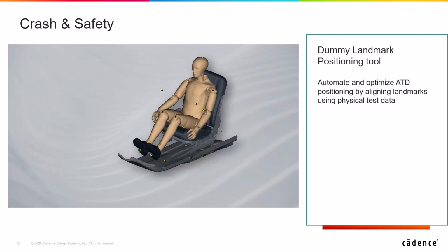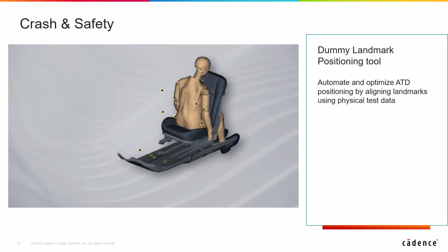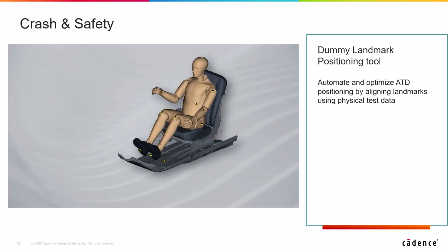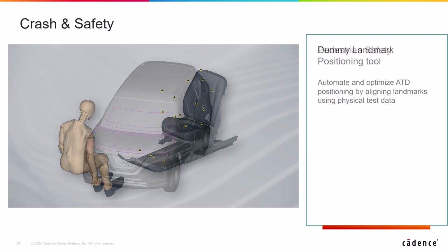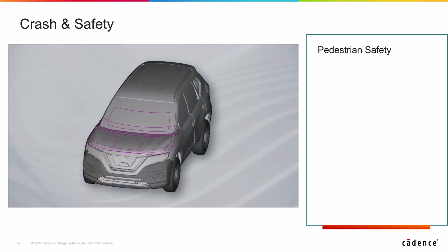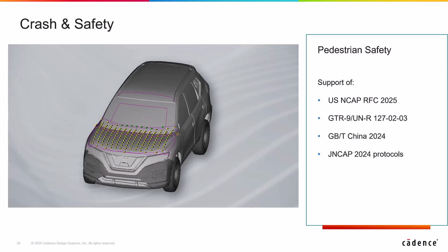The Landmark Positioning tool automatically aligns the dummy by matching key landmarks to target positions based on physical test data. This ensures accurate and consistent dummy placement. For pedestrian safety, the corresponding tool now supports a wide range of new regulations and protocols. This ensures that simulation setups remain compliant with the latest standards.